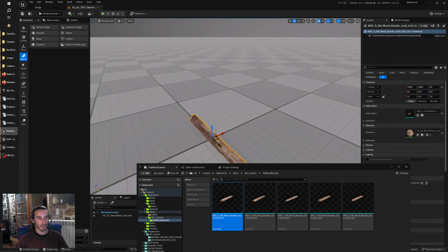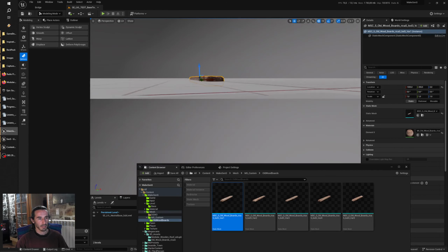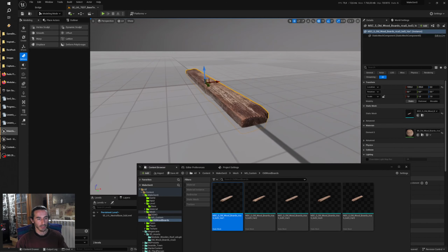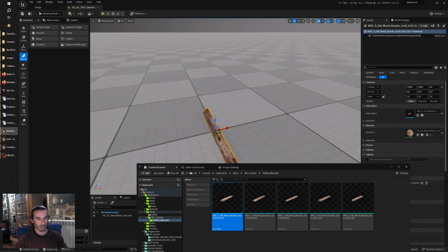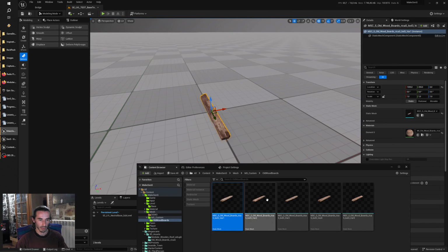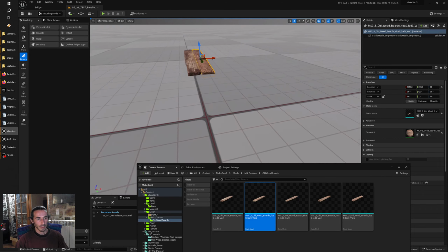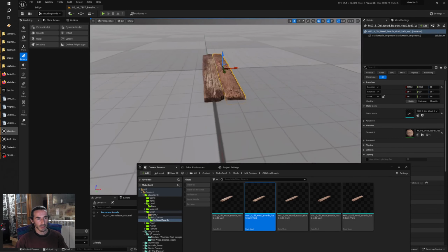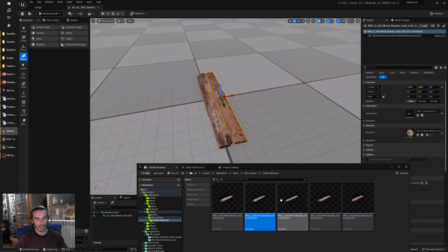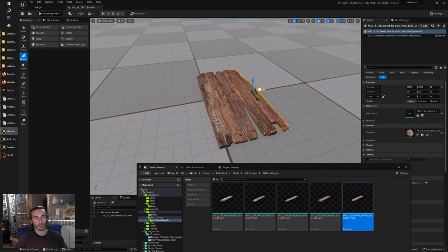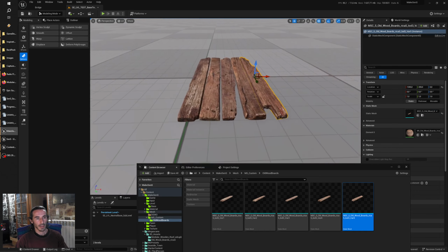And you can place your assets. You can see my pivot point is on the center because it's a wood beam I imported from another project, but it's the same. And you can see all my models are now in a very convenient size, and you can place them very easily in order to create a first wood floor module.